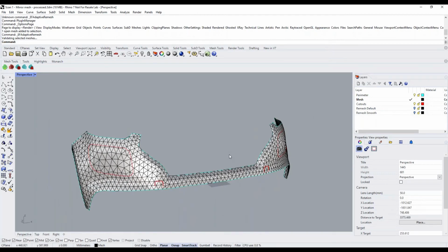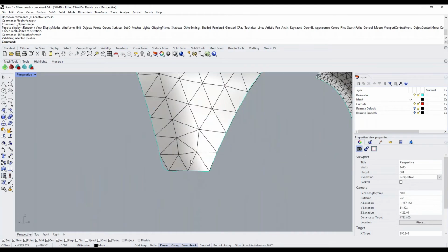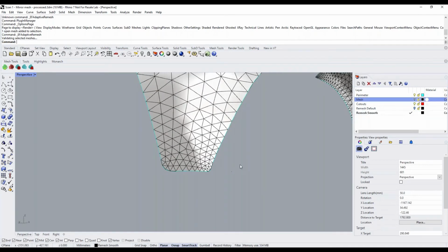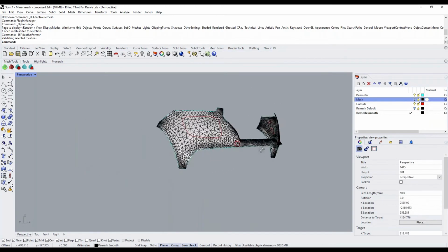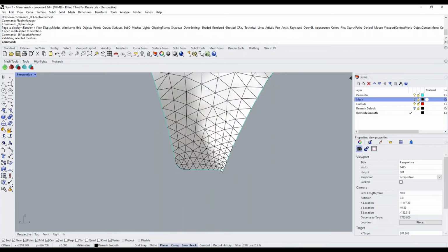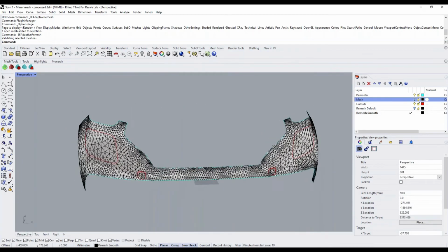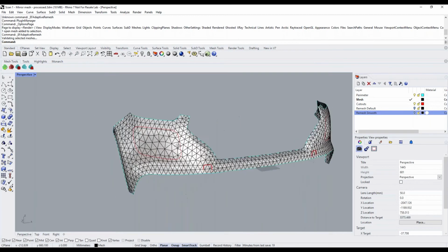So as an example, if I were to tighten up my tolerances to better preserve the curvature, specifically down in these areas here, I would use different settings, and this would be an example of the settings that I would choose. So we do have more triangles on this particular mesh here, but as we can see, we're conforming to the original curvature of the mesh much better. When using the adaptive remesher, you want to find a balance between the number of triangles on your mesh. As you have more triangles in your mesh, that will affect the speed of ExactFlat. So that's why we're using the default settings for the purpose of this demo.